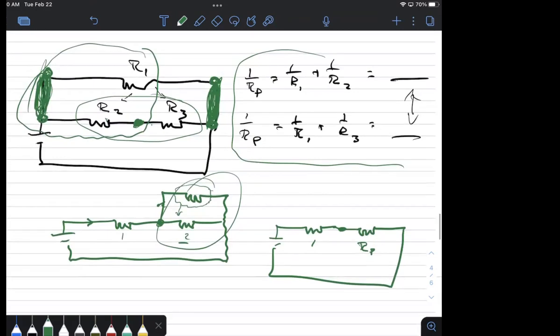So, like I said, I can't say always do series, then do parallel, which is what this needed, because here's an example where I had to do parallel first. What I can say is look at what looks like the easiest or simplest combinations first. Work those out, redraw it, and then see what's left over. A lot of times what starts as very complicated looking will become very simple when you work those small pieces out first.